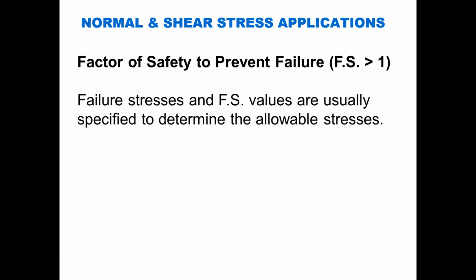And very often in this class, I would give you what that factor of safety is going to be for that particular condition. Now, in the real world, so to speak, your supervisor, your boss, whoever you work for, might tell you to design it to a certain factor of safety, and you would use that particular value based on maybe the standard that's used in that industry or some other sort of standard way of coming up with that factor of safety.